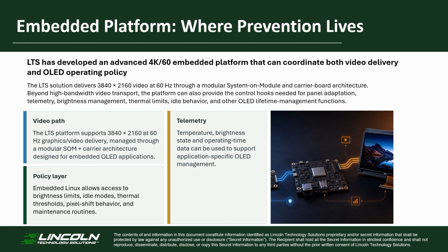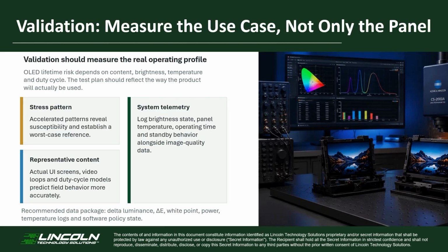Having those capabilities is valuable, but they still need to be validated against the real operating environment. A validation plan should represent the actual product usage rather than evaluating the panel only under generic laboratory conditions. Accelerated stress patterns remain useful. They reveal susceptibility and provide a worst-case reference. Real-world representative content is equally important. Actual user interface screens, video loops, operating modes, and duty cycle models often predict field behavior more accurately.